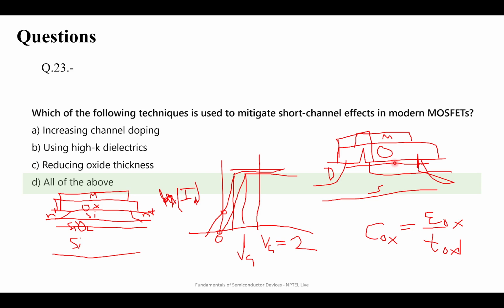But here you have only a very small thickness of channel, so you can convert this whole channel to n-type, and you will have very few holes present from your substrate. So it will improve your gate control very much.